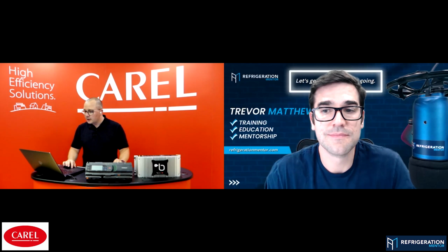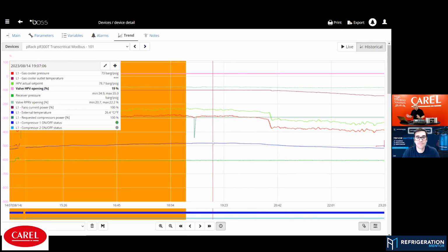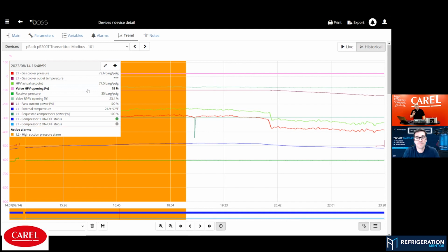we were thinking, okay, after we have checked, refrigerant is enough in the application. The rest is running well. Our receiver pressure valve is doing what it should do. And everything is running perfectly, except the HPV valve. So we said, okay, we can do the following. We can turn off, we can take a look. Normally, the application is turning off in the night because we don't have some loads. And if our controller stops regulation, it will reset all the valves.